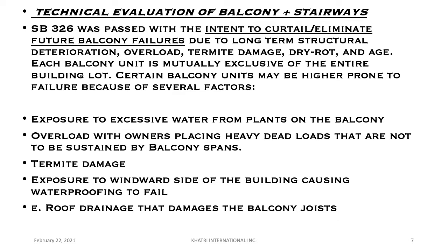Well, the main thing is long-term deterioration. They are very, very substantially overloaded. I've seen a lot of that as I look at cases around the state. Termite damage, definitely a major cause, which from water causes dry rot and just age. You know, balconies, wood doesn't do too well once you pass a certain number of years if it's not maintained, if it's not protected, if it's not waterproofed, if you don't take care of it, it's going to age, it's going to eventually come apart.